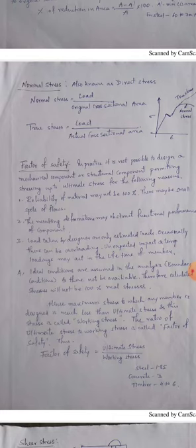Therefore, if you consider RCC or steel, whatever your estimated loads are, they should be multiplied with some factor of safety. The factor of safety varies with the type of material. For a steel structure, the factor of safety should be 1.85, concrete 3, timber 4 to 6.